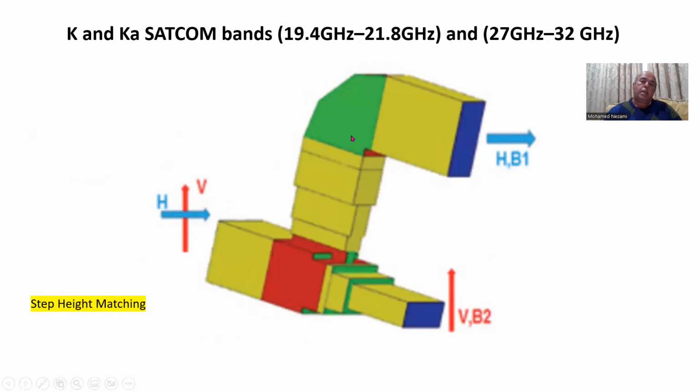So you can see that when we design it, we start out with this. We say, okay, we know the dimensions of this because we know the incoming frequency. So we can pick this from the EIA standards for waveguide dimensions. So this piece is a natural fallout from the band that you're working in, and the same thing for the branching branch here, and for this one as well. So the dimensions are basically always given as an EIA standard. You pick those.